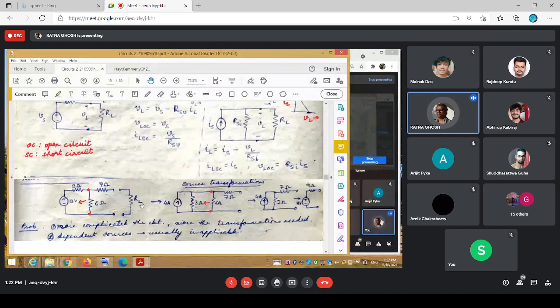For this particular load resistance, it will view this whole circuit as equivalent. An equivalent source would be 8 volts with an internal resistance of 9 ohms. This is what this load sees this whole circuit as. It need not know whether all of this is there or not. It can simply treat this as a voltage source with a series internal resistance.